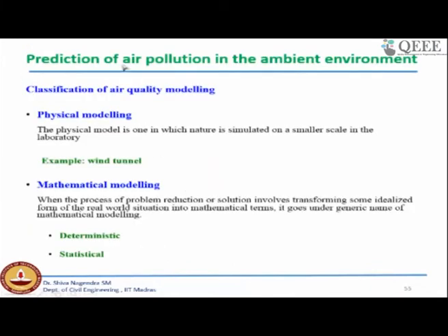Okay, so you can classify the models into different types. Broadly, you can classify them into physical modeling, mathematical modeling, numerical modeling, or statistical modeling. Physical modeling is nothing but simulating the dispersion conditions from any source on a lab scale, on a smaller scale in the laboratory. One example is the wind tunnel. The wind tunnel is widely used to simulate air pollutant dispersion from various sources.